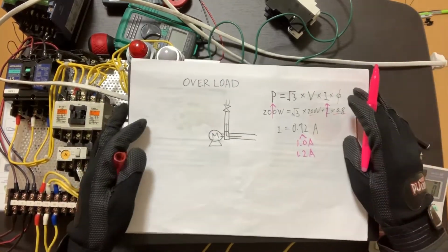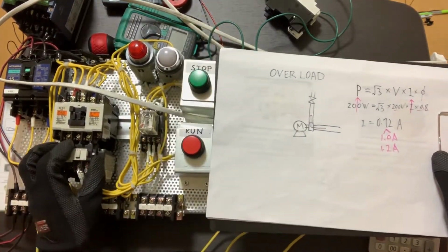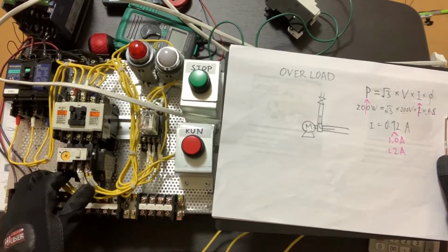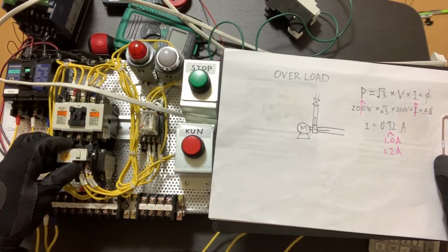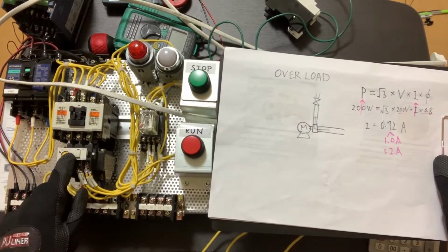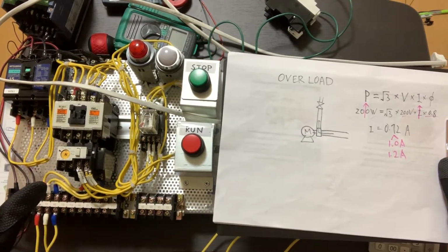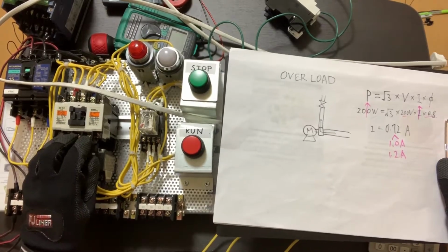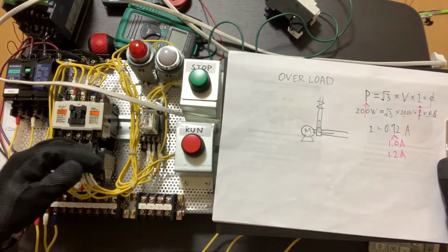So this is why protection devices are needed, like a thermal relay that can prevent this by detecting overcurrent above a predefined value. If they set 0.7 ampere, and overload happens and the current exceeds 0.7 ampere, they can detect such a failure state and interrupt for safety.